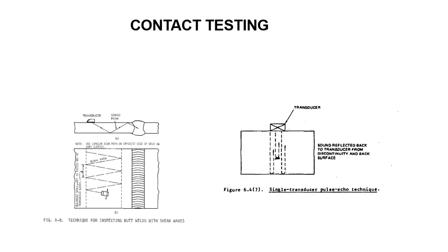In contact testing, the transducer is placed in direct contact with the test specimen with a thin liquid film used as a couplant. On some contact units, plastic wedges, wear plates, or flexible membranes are mounted over the face of the crystal. Transducer units are considered as being in contact whenever the beam is transmitted through a couplant other than water. The display from a contact unit usually shows the initial pulse and the front surface reflection as superimposed or very close together. Both near field and dead zone effects are present in contact type tests.